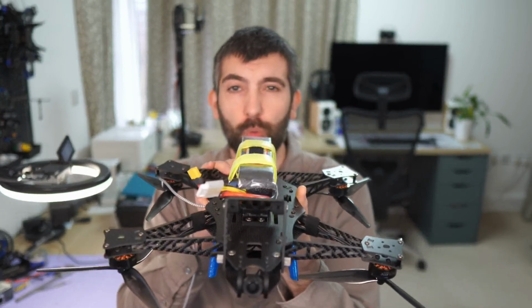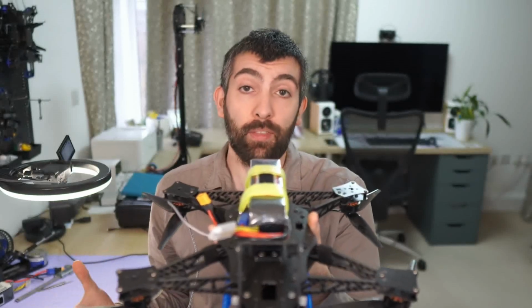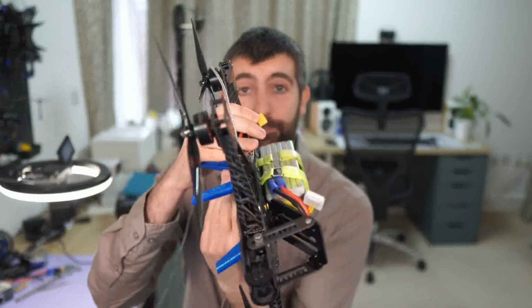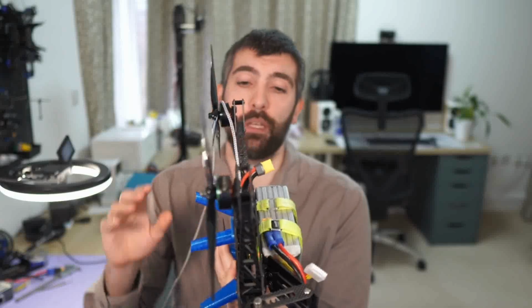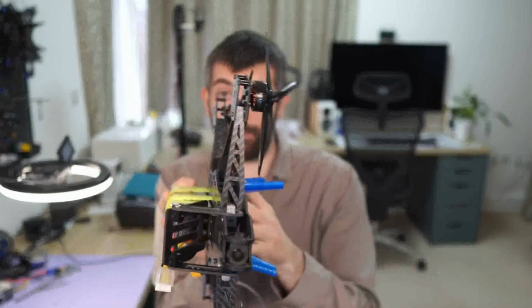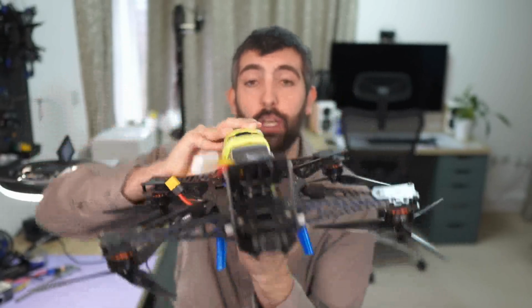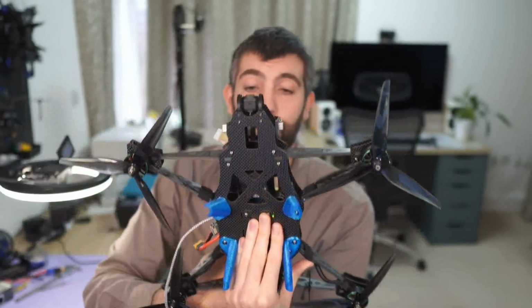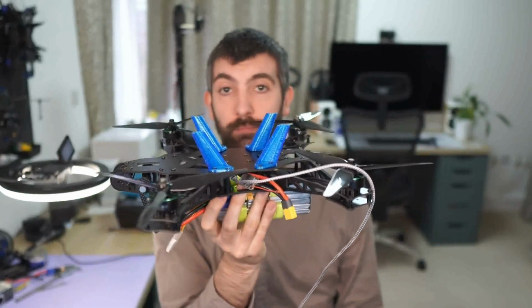To calibrate the accelerometer, you just need to follow the instructions on the screen. So you click Calibrate Accel, and it will tell you to hold the drone level. Just hold the drone approximately level, keep it nice and still, and then click Done. Then you'll be told to put the drone on its left side. And again, when you've done that, hold the drone nice and steady and click Done. You'll then be asked to do the right side. Again, click Done. Then nose down, click Done. Nose up, click Done. And finally, hold the drone on its back, nice and level, and click Done.